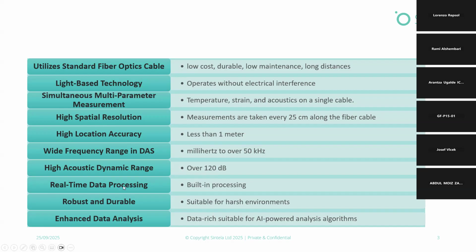Real-time data processing is another one, and there are a lot of advancements in this space. That has been one of the challenges of DAS specifically, but that's rapidly being overcome. And it's really suitable for harsh environments because we are dealing with fiber optics cable that can be manufactured for really high temperature areas or high pressure applications such as oil and gas. And with enhancements in data analytics and AI power, I think DAS really gives us a lot of opportunity to do large scale, high resolution monitoring at much faster speed as we improve the data processing routines and algorithms.